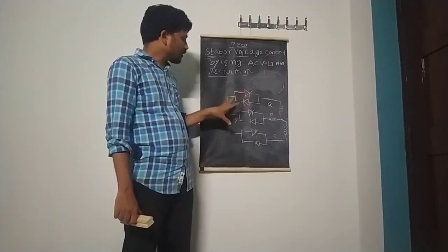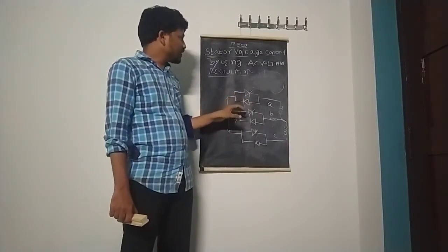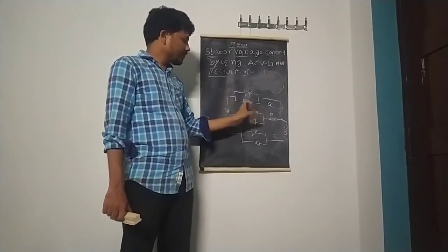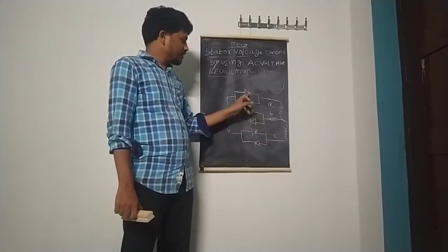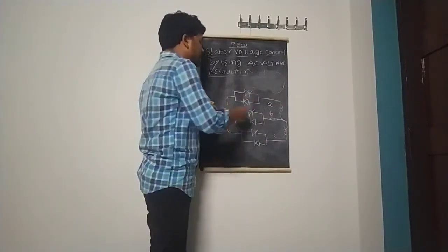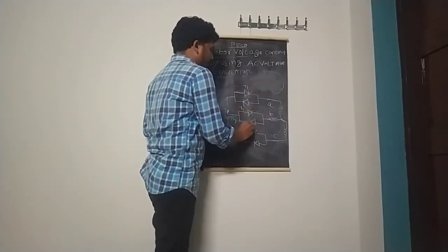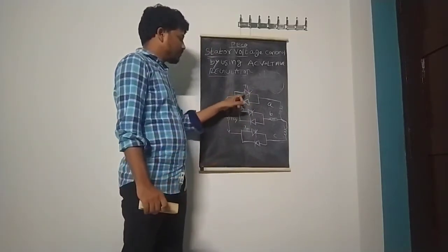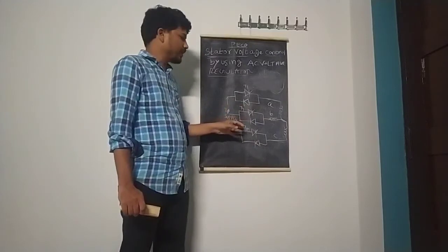So this is about the diagram of the stator voltage controller by using the AC voltage regulator. Is it clear? The three-phase supply is not directly given. With the help of this regulator, we can control the speed. Okay. Here, let us say these are thyristors 1, 3 and 5. Thyristors 1, 3, 5 with respect to the supply are displaced from 0, 120 degrees, 240 degrees. Each has a phase displacement of 120 degrees.